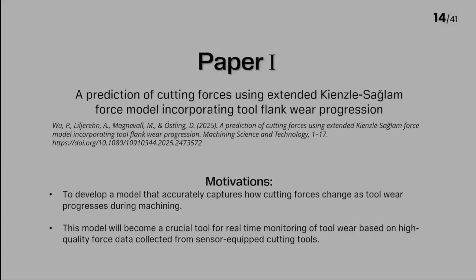The first publication is about the prediction of cutting force using an extended Kienzle force model, incorporating the tool flank wear progression. This work is driven by two motivations. First, we need to develop a model that accurately captures how the cutting forces change as tool wear progresses during machining. And this model will become a crucial tool for the real-time monitoring of tool wear based on the high-quality force data from the sensorized tool.